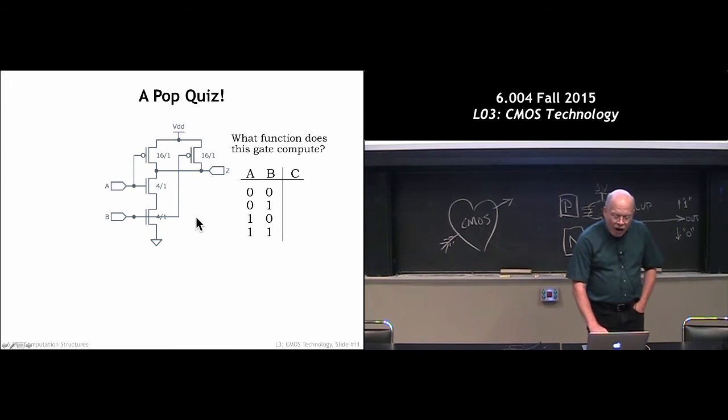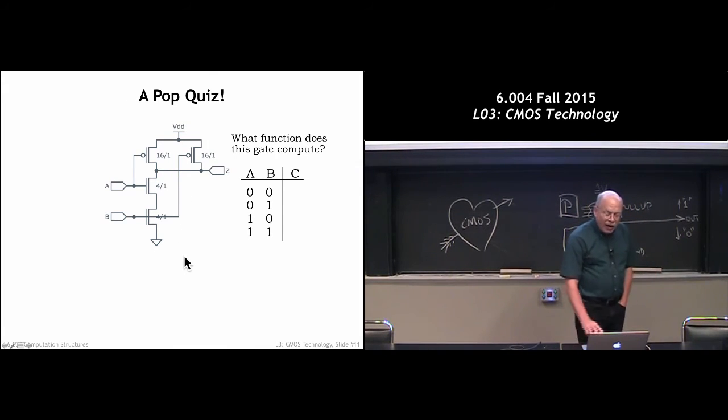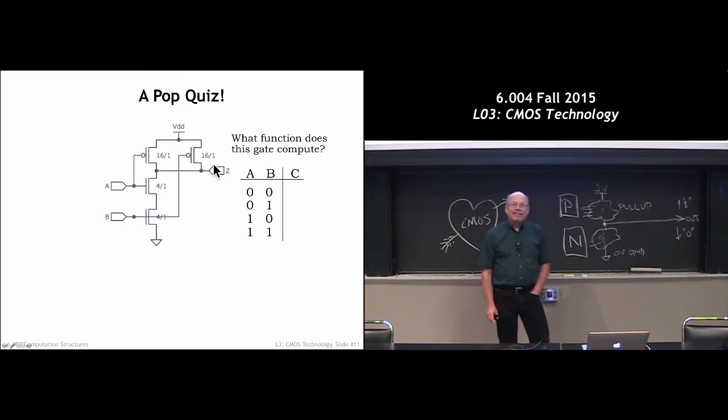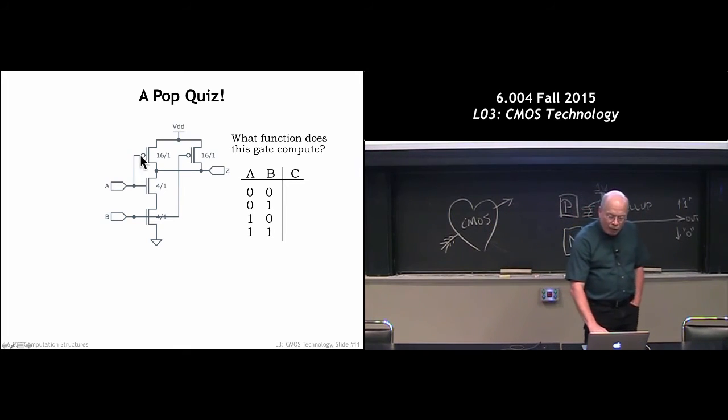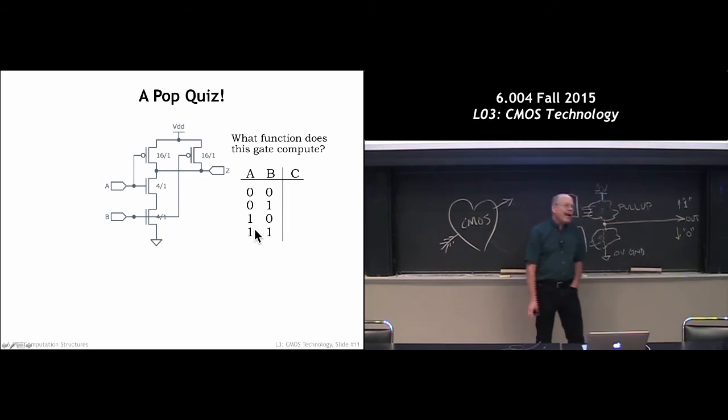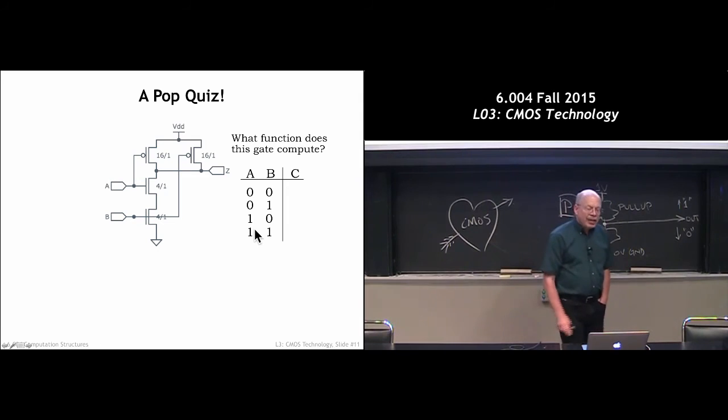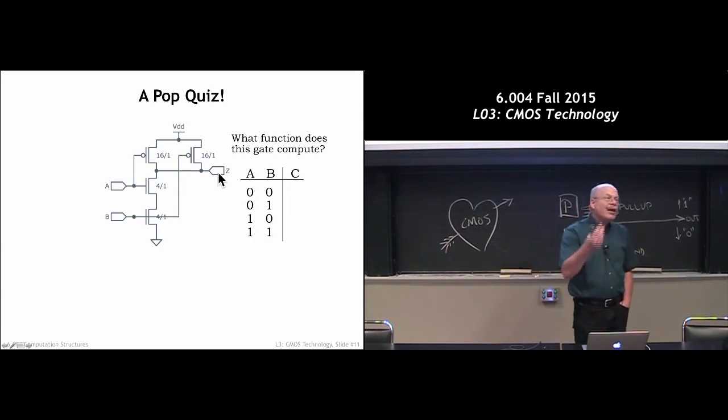So we want to figure out how this logic gate works. It has series N FETs and parallel P FETs. So this is a combinational device. Here's the beginnings of a truth table. We have two inputs, A and B. So that means I want to look at all possible logical combinations of digital values for A and B: 00, 01, 10, 11. For each combination, I want to figure out the value that the output node will get eventually. We give it enough time to change.